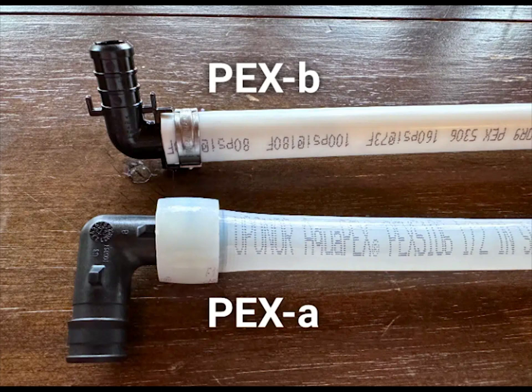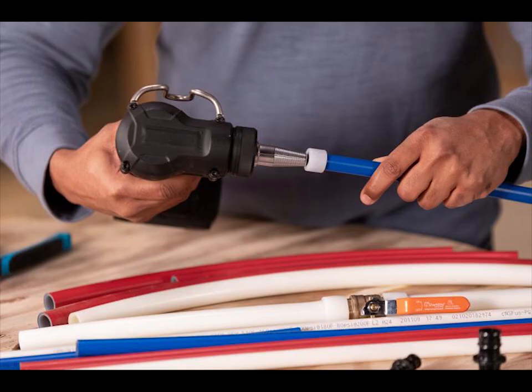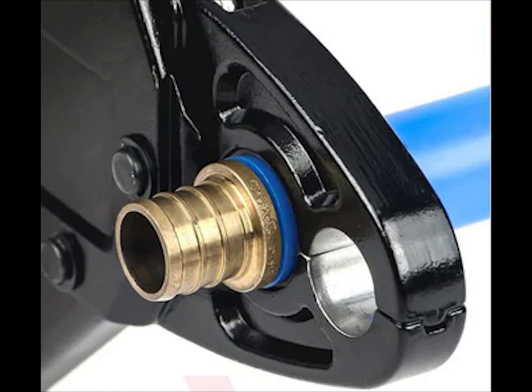I used PEX B. It uses internal fittings and crimps. I needed 1/2-inch pipe, Type B, PEX. Type A PEX requires an expansion tool as shown here. Type B PEX requires a crimp tool or SharkBite.